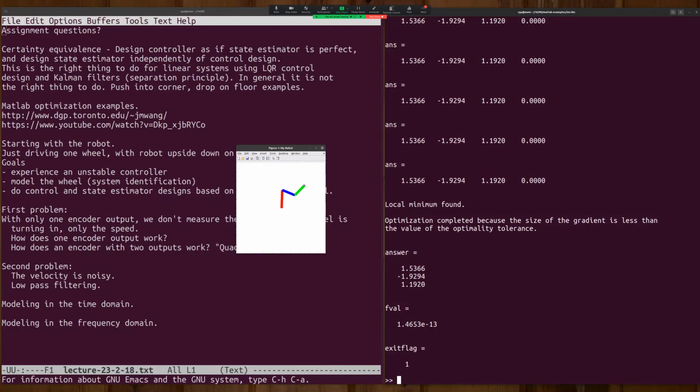You could include information on the angles from the other joints. And how would you use that information? So if you have the angle for the blue link, then you can specify what orientation that's at, and you can use that to minimize the distance of the endpoint.